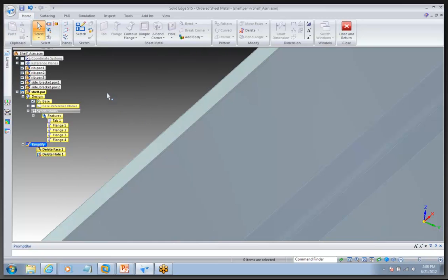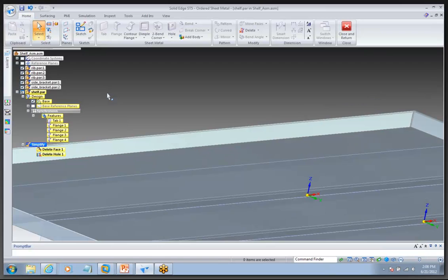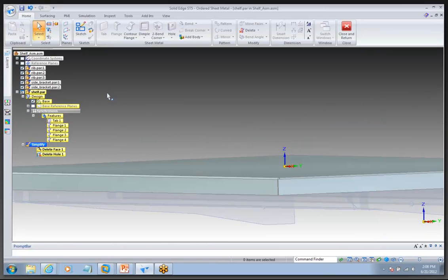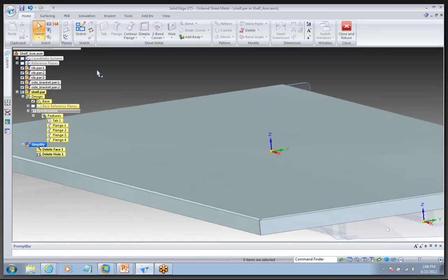the surface element. Surface element is not a 2D element. People always say that because it's represented by a surface, but the reason for that is because you only use 1 through the thickness because it does have the rotational degrees of freedom.